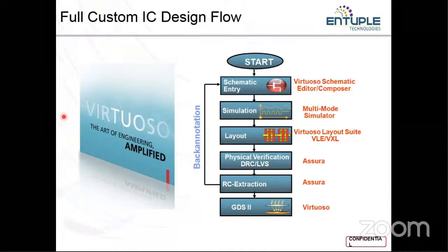These rules are there in order to avoid some effects, and they are called design rules. So the first step is checking those design rules, whether your layout has been designed by considering them, like minimum size and minimum spacing. That is what we do with design rule check, or design rule compliance, and that is what we call DRC. And the next step: you have a schematic.